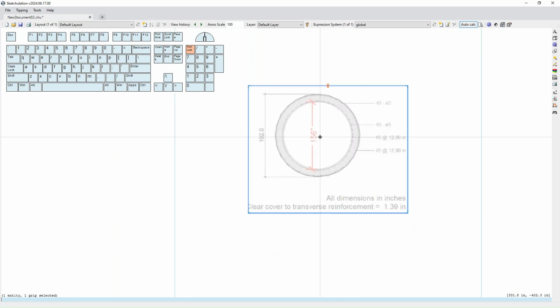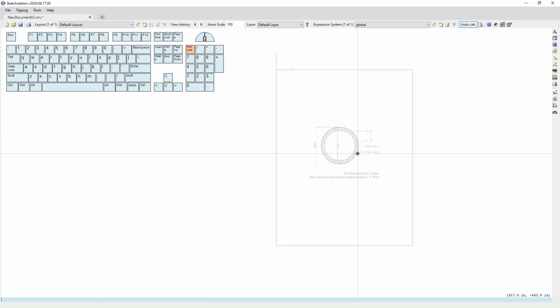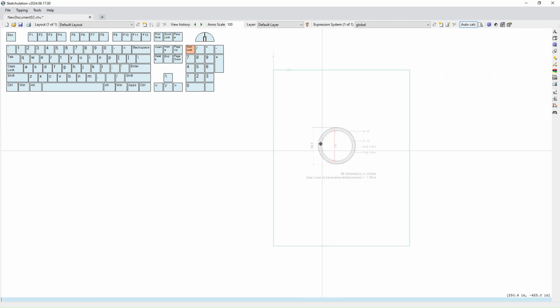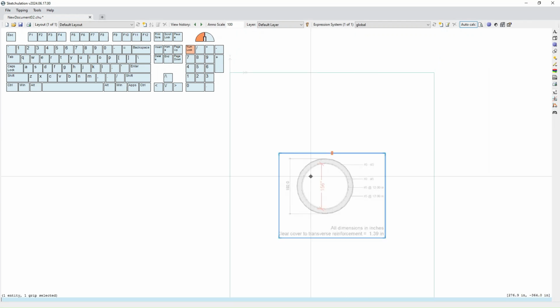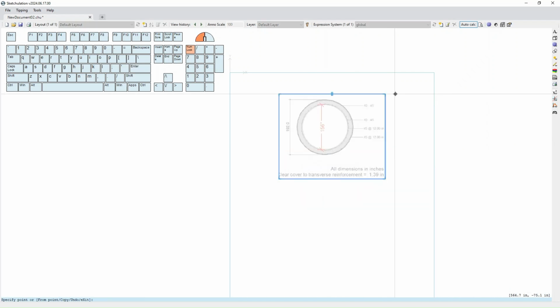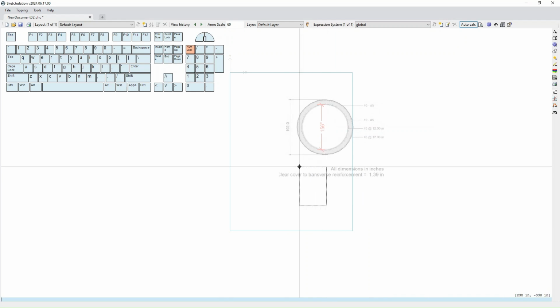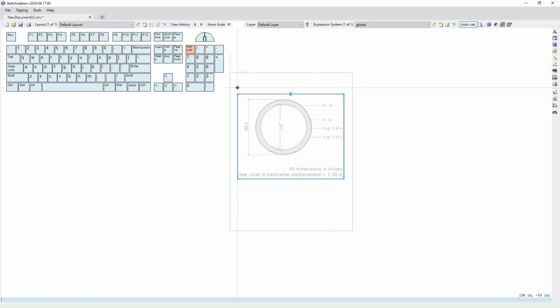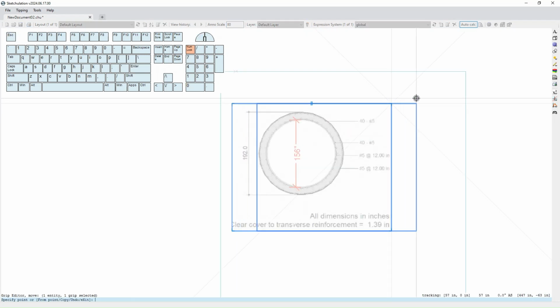I'll go ahead and change the opacity on that, bring it down a little bit, say to 0.3. This should be good. So it's a little faded. And I may change my annotation scale a little bit because this is my page layout, and it might be nice to have it slightly bigger on the page. So let's say I take that down to 60, something like that. Maybe it's too much. Maybe 80. Okay, something like that, just for presentation purposes.